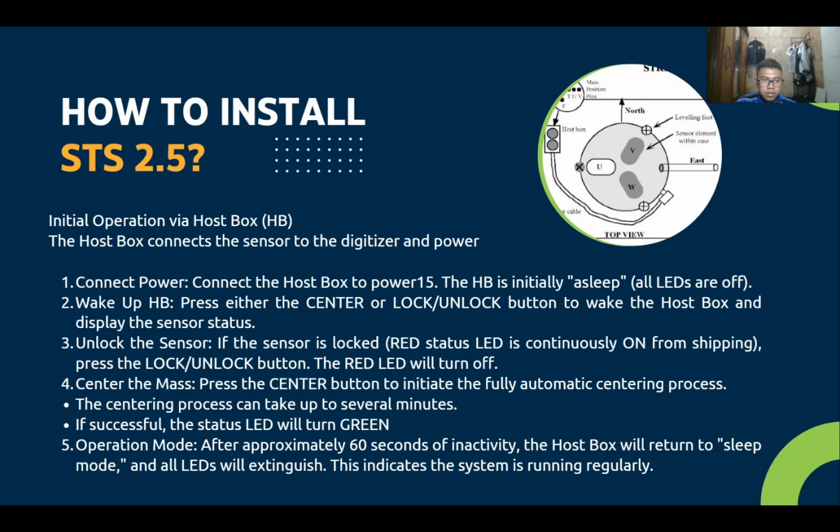Last step is initial operation via the hostbox. First, connect power to the hostbox, because the hostbox is initially asleep and all LEDs are off. Then press either the center or lock/unlock button to wake the hostbox and display the sensor status. If the sensor is locked, press the lock/unlock button, then the red light will turn off.